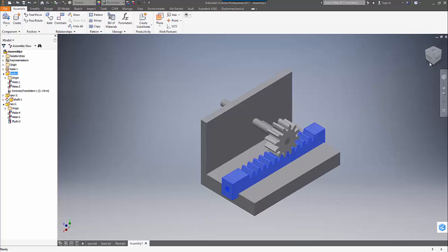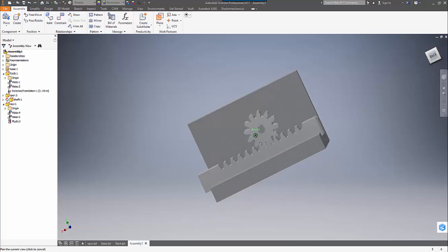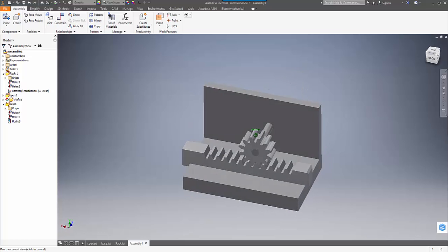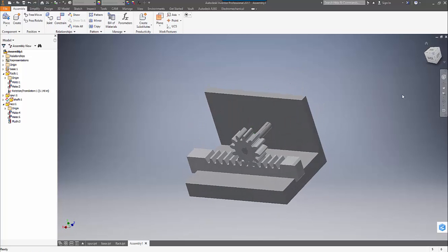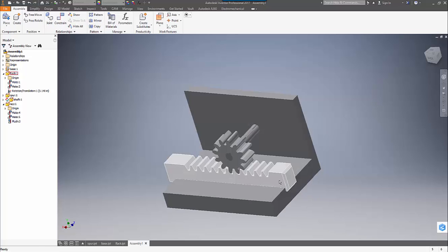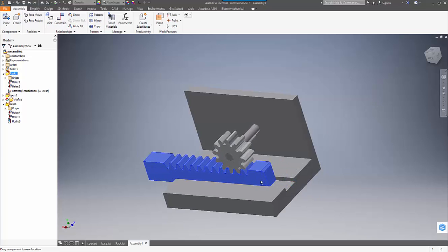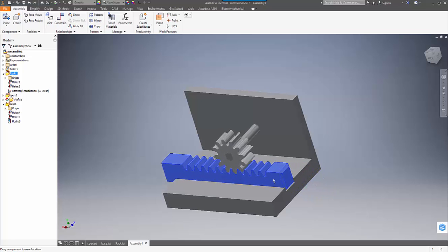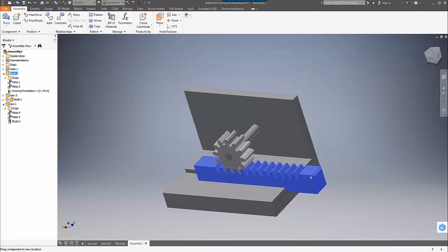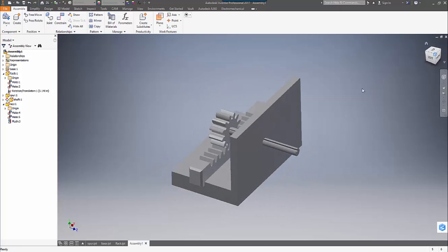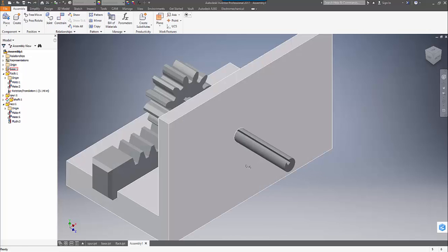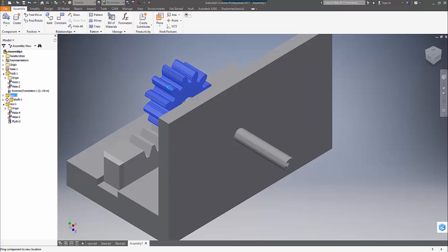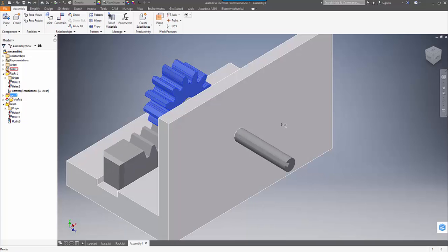So now the last part of this presentation is all about how to make this work within the Inventor software to actually control how far this rack and the spur gear turn. And this is called a drive constraint. Okay, it's called a drive constraint. And so the constraint that we're going to apply, and most of the times the constraint that we do apply, is a constraint called an angle constraint.